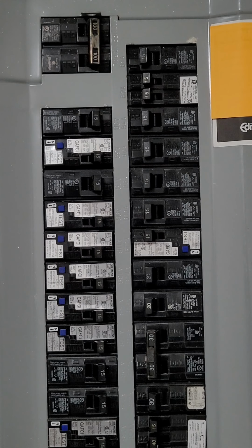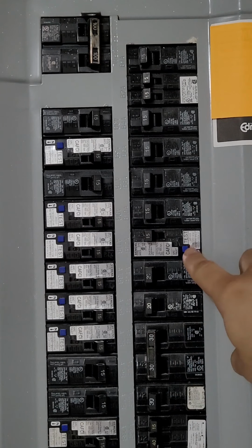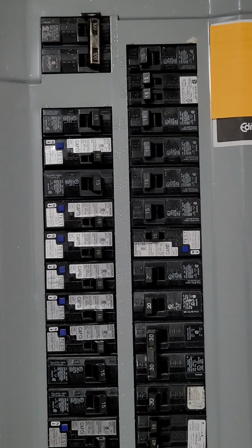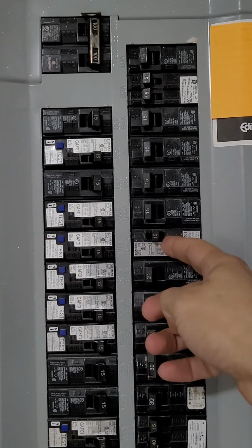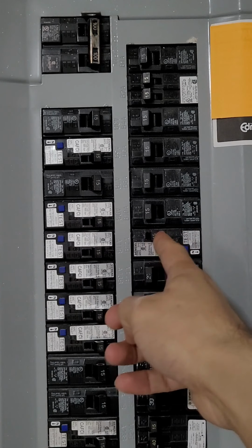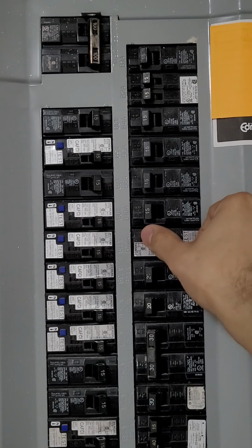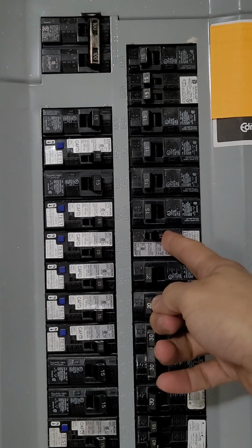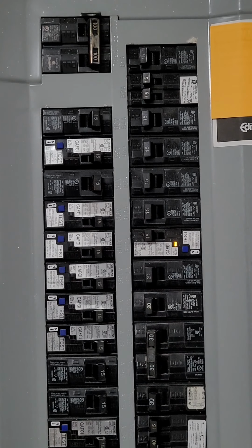But sometimes breakers, if they trip or you purposely shut it off, they kind of stay in the middle. For example, I'll just press this test button and you will see the breaker is in the middle. That means the breaker won't turn on if you take it directly from this middle position to on, and it will go back to the middle. So put it completely off, and in a few seconds you can just put it back to on position, and then your circuit will be on.